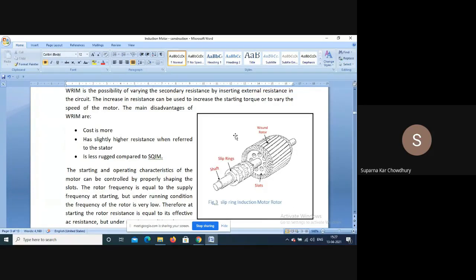But one advantage of the squirrel cage motor is that the squirrel cage winding is adaptable to any number of poles. That is, if there is a provision of reconnecting the stator winding for two different numbers of poles, say 2 and 4 poles, then the rotor itself always adjusts to the number of poles, because the EMF induced in the rotor is according to the stator current.